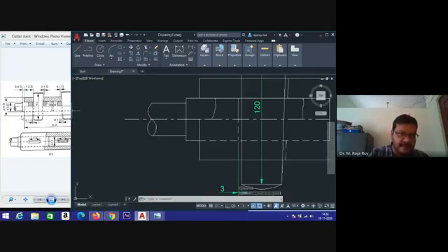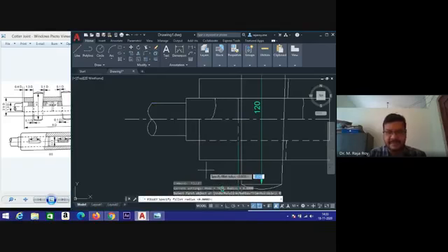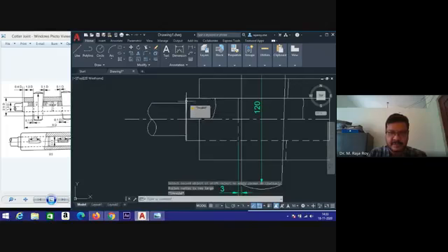So here we have to apply small fillets. Go to fillet command. Select this. Select radius. Radius, you select some 5. Select this and this. Fillet 5 is not possible there.